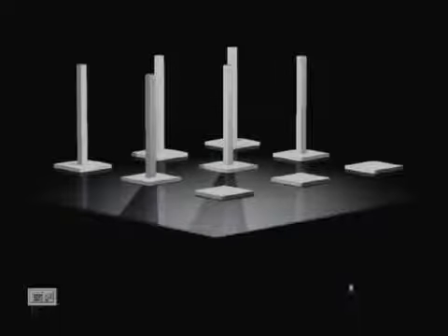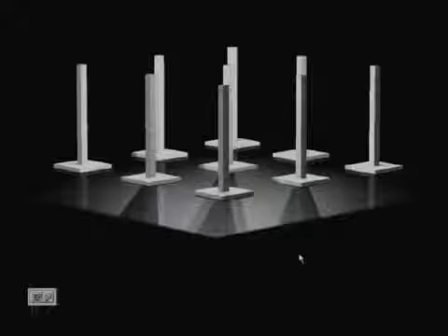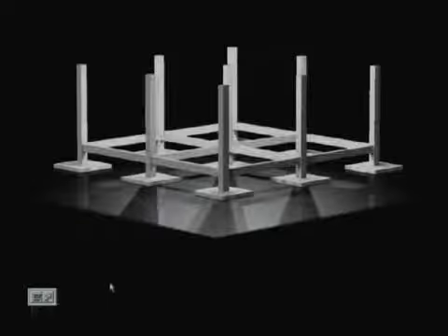the second level and third level. And these are all tie beams. For a wall we generally do not provide a wall footing; we start from this tie beam, which will take the wall load. We can also take it for the frame, that connection we also consider, but we generally use it for walls.